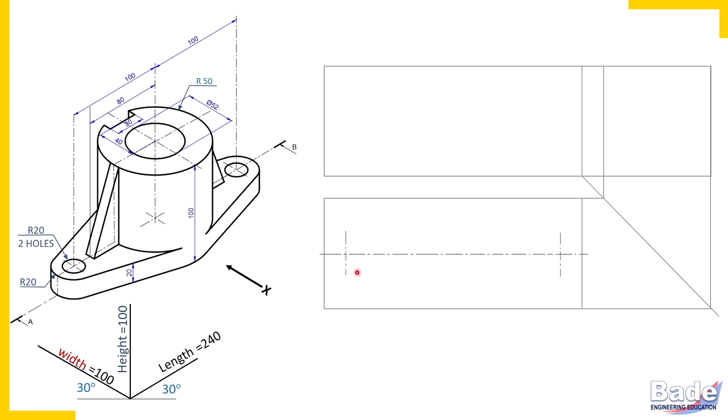Now with these centers, draw these curved edges, but try to understand these curved edges are not semicircular or quarter circular. These edges on both the sides, on the right side and on the left side, these curved edges are longer than quarter circular edges but shorter than semicircular edges. But right now we don't know exact length of these curved edges. So draw thin curves first.